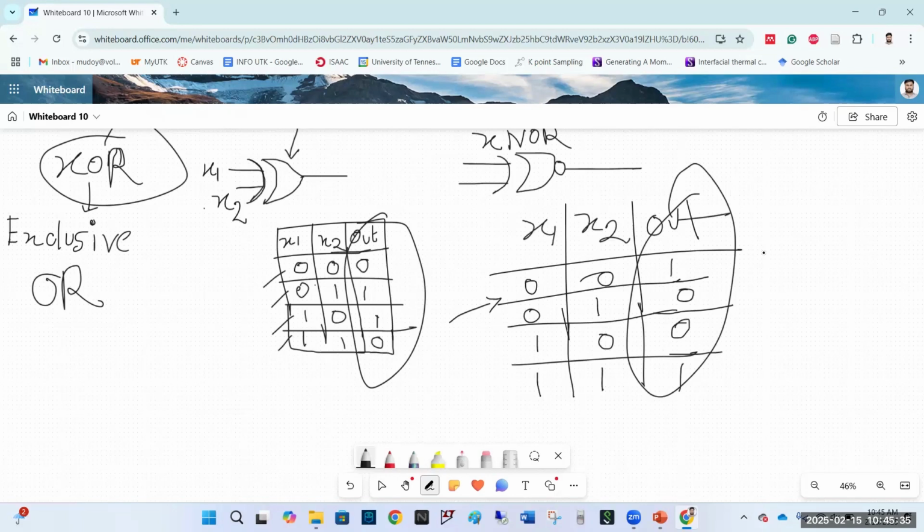Yeah, sir. Yeah, of course. Search also, and it's a good application. Another can be password verification. Because you will have a saved password, and the user will give some input. It will match. If there is a match, then approve. If there is no match, deny. So this kind of application can be done using XNOR. XOR and XNOR are pretty much opposite.